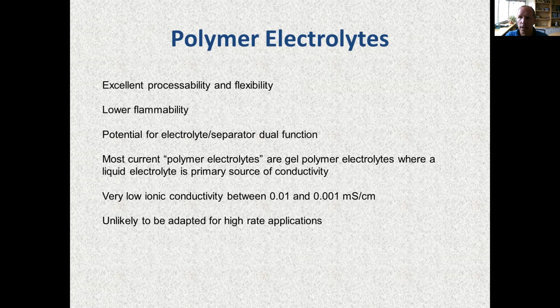They don't go away. And in terms of the pure polymer electrolytes, which are typically polyethylene oxide, the conductivities of these materials are still not very high. And once again, the wettability of the electrodes is relatively poor. And so I would say in terms of just the pure polymer electrolytes, they're not likely to be adapted for especially high rate applications. Some of these gel polymer electrolytes are already in use in commercial cells, but they still have a lot of the same disadvantages of the liquid systems.